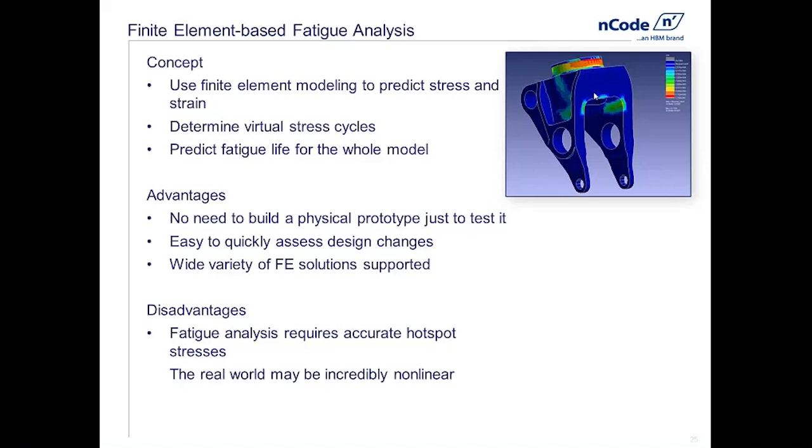And then lastly, the real world can be very nonlinear in some ways. So sometimes the modeling we do is a simplification of the actual, say, geometric loading or maybe impact or other things like that. I think that this disadvantage is going away over time as we have more robust finite element solutions out there. But we still have to think about what is the difference between what we're modeling and what's actually happening out there in the real world, and then try to rationalize that difference or understand it in our finite element-based fatigue calculation.